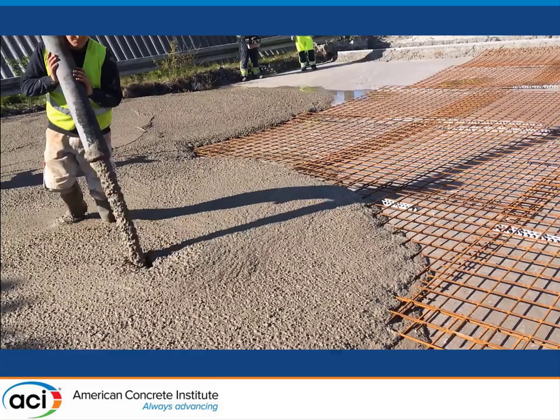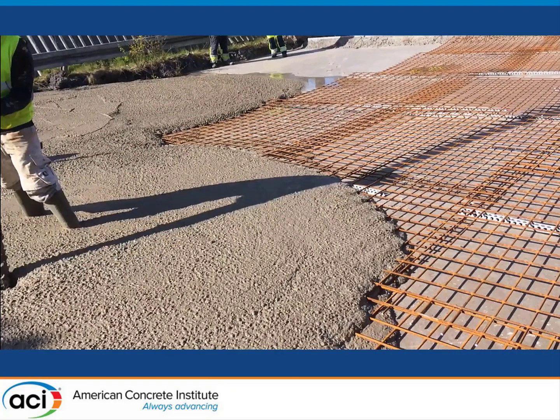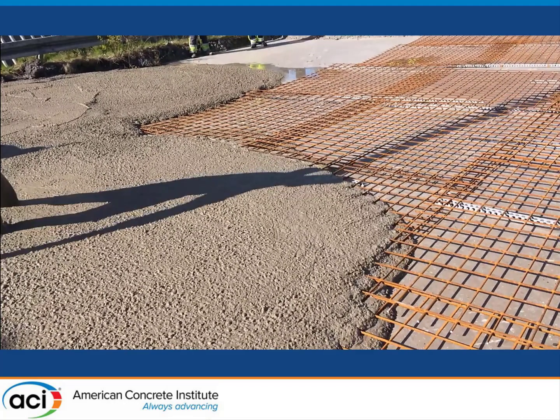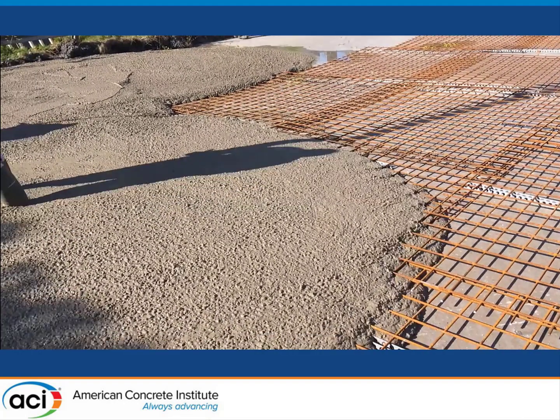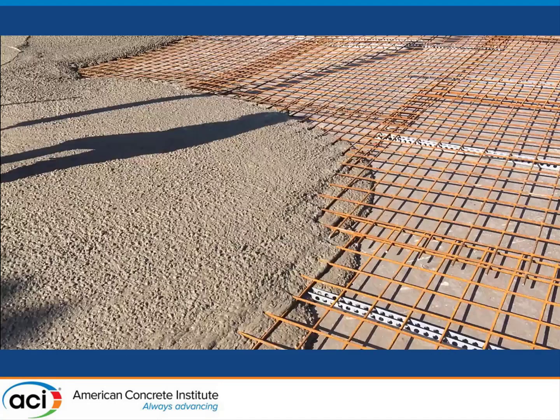We, of course, see that we need to use somewhat more, 50 to 75% superplasticizer, but also, and I'm quite sure that we'll hear something similar from the talks later on today, the admixture manufacturers are really good at optimizing their admixtures, and we're very optimistic that by the end of the day, we don't need higher doses of superplasticizers than today.